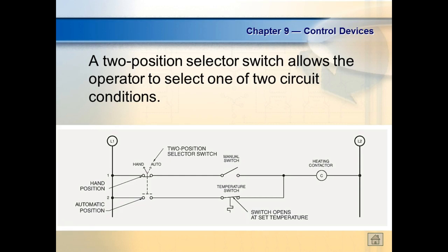So let the switch have two different wires. Well, actually, we'd have four. This one would have four. We could have a selector switch that's got more than two positions. I've seen them that had four. You're flipping through, and each one of them would open a set of contacts, and that's why it would be very important to get the drawing. It shows you what contacts are open.